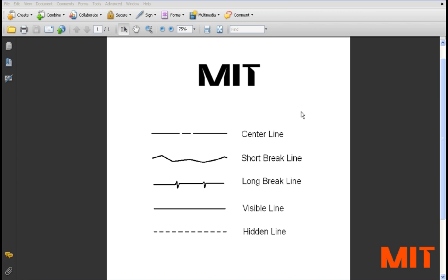Another case where you're going to see center lines is if we're looking at a circle dead on. We're going to have a center line going from the top, and a center line going across from left to right. So with center lines, what we're able to determine is the center of the radius. So it's showing the center radius of the circle that we're looking at. If we see one line, it's just showing lengthwise where the center line is, and if we're looking at it dead on, it's going to give us the exact point where the 2 center lines come in contact with each other.